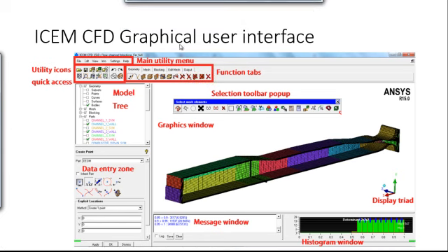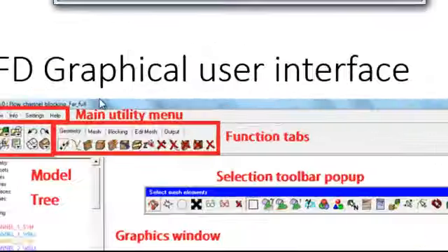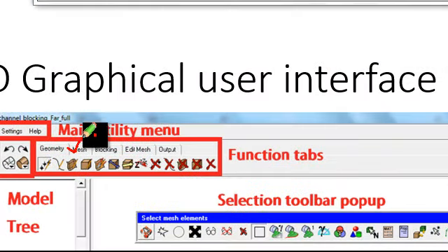After that, there comes the mesh menu, where you can define the mesh parameters. You can define the general mesh parameters, the periodicity, the volume mesh parameters, the shell mesh parameters, and the mesh sizes on the parts, curves and surfaces. Also in the mesh menu you have the option to compute the mesh using different methods like Delaunay and octree. Then there comes the blocking.